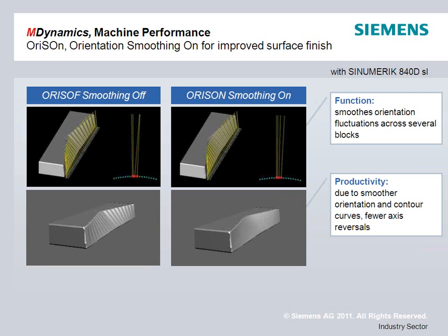This really comes into effect when you get larger machines. And like I was saying, even if you are dealing with something like composite trimming, where it's a thin part and you do have more tolerance with respect to surface finish than aluminum structural parts where you've got a cutter buried in 4 inches and you're using the shank of it, it'll still end up giving you faster execution.